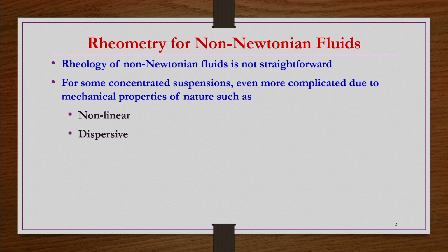Further, the complications may even increase for some kinds of suspensions where the mechanical properties may be nonlinear, dissipative, dispersive, and thixotropic in nature. When the mechanical properties of some concentrated suspensions have such a nature, then rheological measurements of such non-Newtonian fluids or concentrated suspensions become even more difficult.